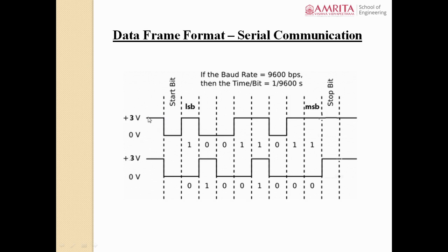For the time being, let us take that you are going to transmit data such as 1001 1011. If you are going to transmit this data, what will happen? Whenever you initiate the transmission, the TX line will be pulled down from VCC to 0.